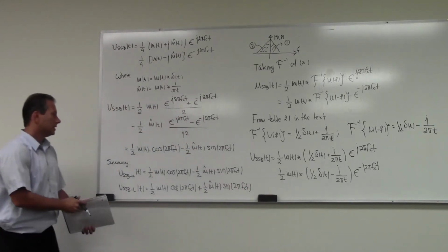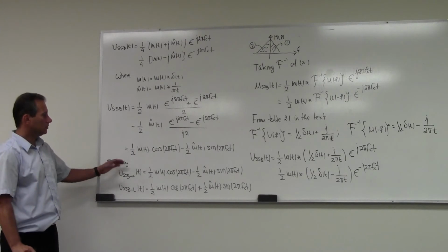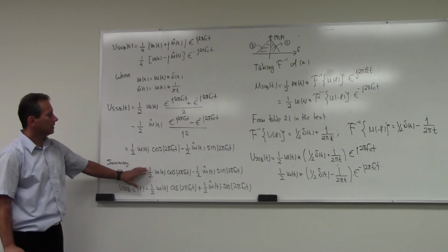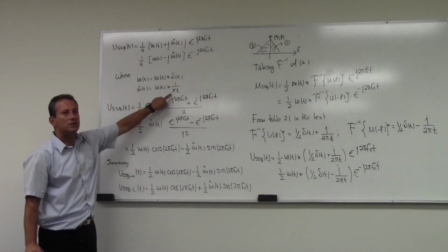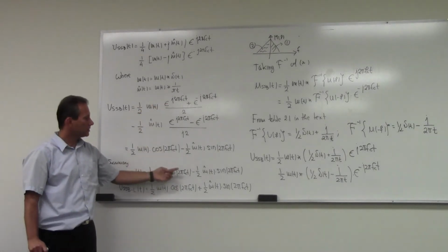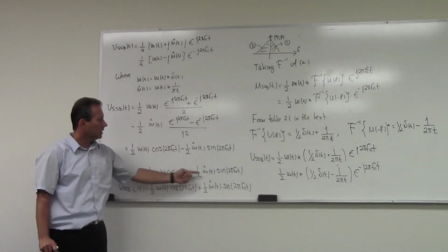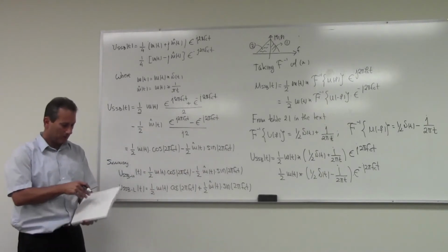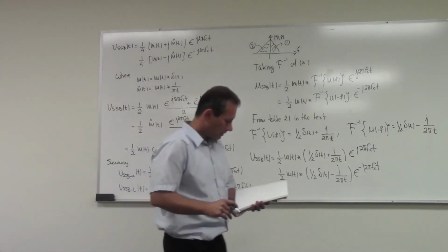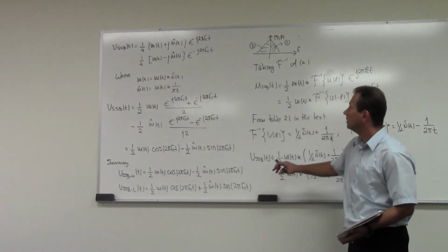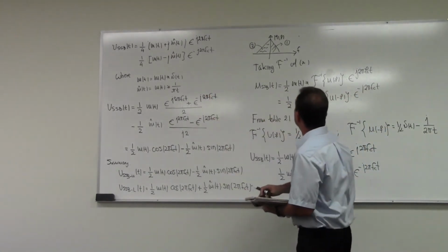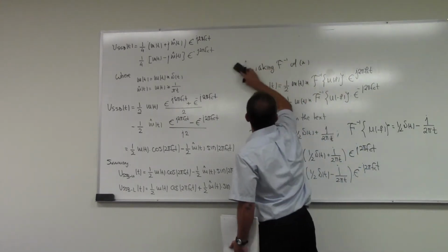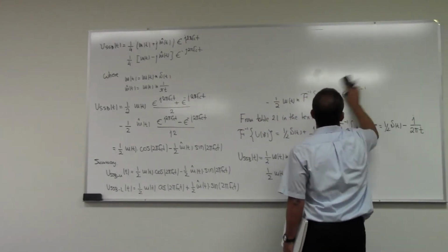So we've learned that we can generate the sideband by doing all the processing at the baseband. The only thing that is left now is to understand what this filter is. What kind of processing will take my signal m of t and give me this m hat of t? So let's take a closer look at this filter with the impulse response 1 over pi t. What kind of processing is that?